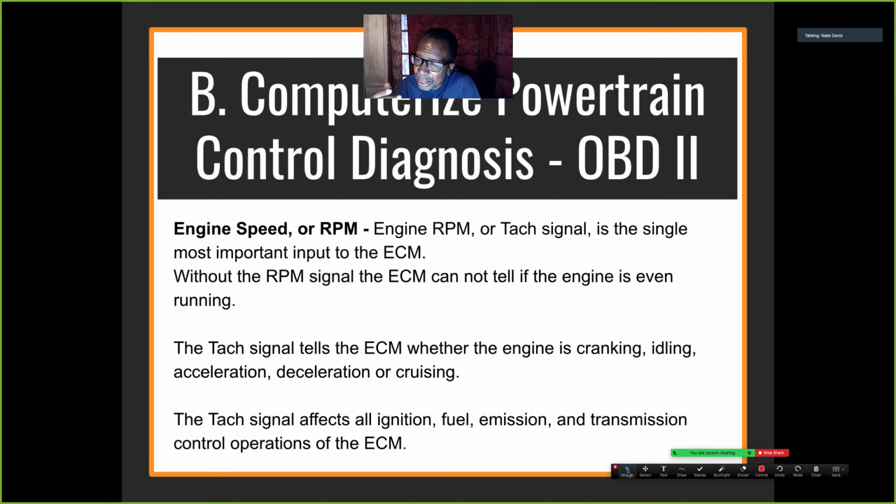So, decelerating. If it does that, it's going to downshift the transmission, or turn off the injectors in a lean mode. Put the injectors in a decel mode when you're really not. Remember, when RPM increases, it's a command to the PCM for more fuel. As soon as the PCM/ECM sees a decrease in that frequency signal, it thinks you're letting off the gas pedal or turning the car off. So it's going to respond to that.